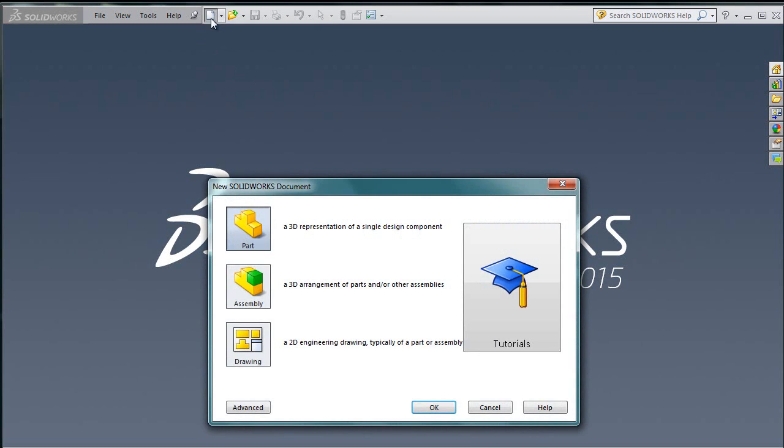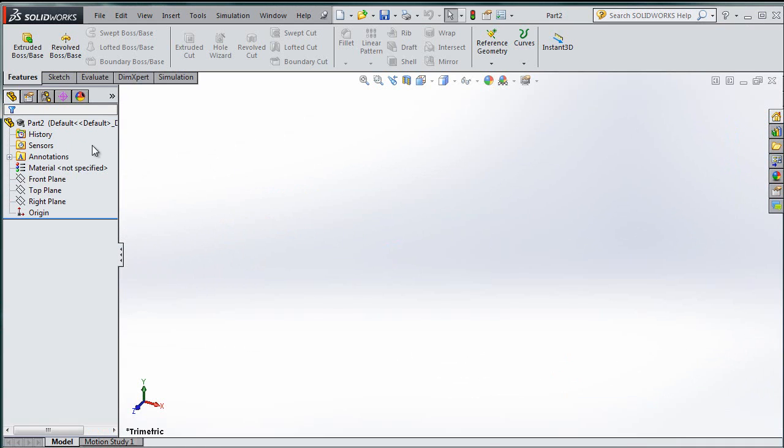So here we are in SolidWorks. We're going to create a new part to correspond with what we're doing. Now the first thing you're going to notice, or maybe not, but eventually you will, is that this coordinate system is stupid, in the context of engineering stuff like what we're doing, because normally we expect z to go up, x to come toward us, and y to go out. Now you'll see it still follows the right-hand rule, x cross y is z with a thumb. So it's still okay, it's a totally legit coordinate system.